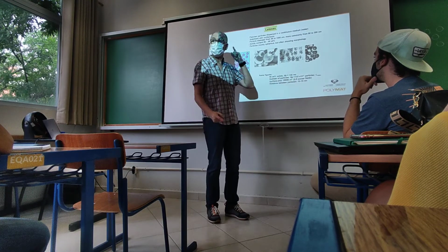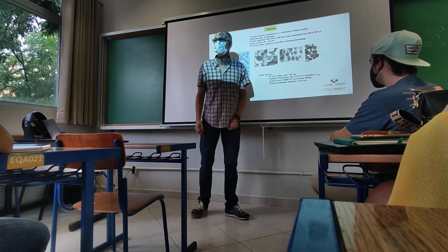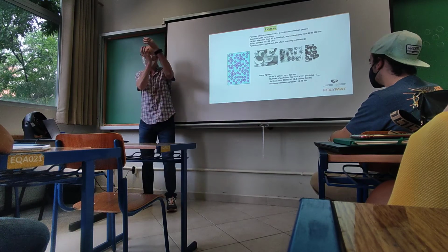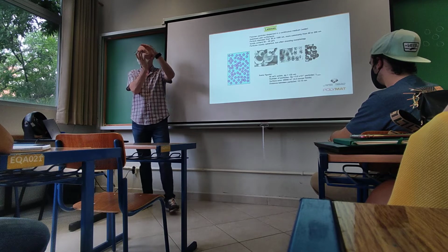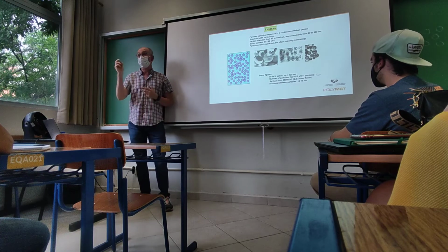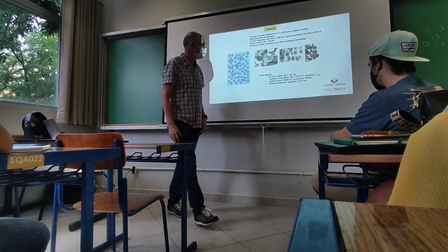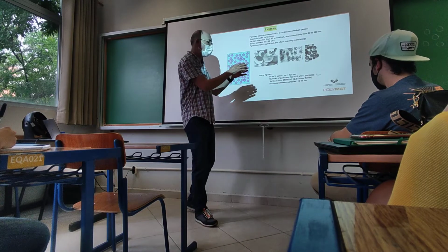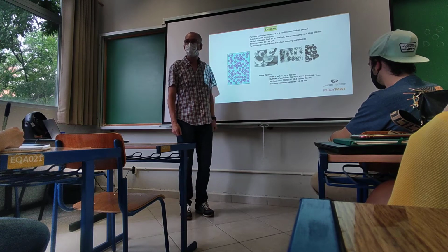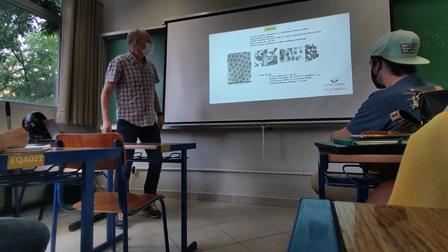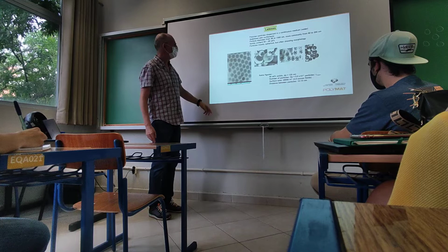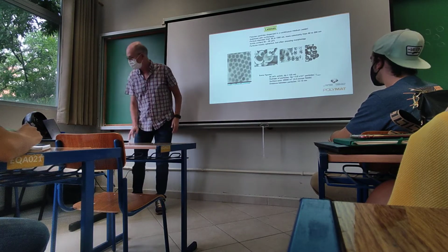As you can see here, in 1 liter of latex, the surface area of the particles is 2.5 times 2 soccer fields. Okay? In 1 liter. So you have this area in 1 liter of dispersion. Okay? So the surface area that you have is tremendous. Okay? Because of the nanoscale of the particles. And the distance between the particles is approximately between 10 and 15 nanometers at this concentration, at 50% solids. Okay? This is a transmission electron micrograph of the dispersion. Okay? So this is what polymer latex is.